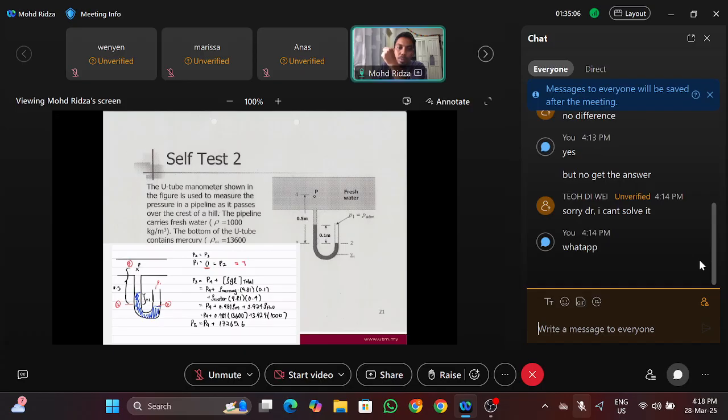rho. I think maybe you haven't applied it, because I think you assume 0. You have to use rho of water, because it's saying 10.3 meters of water. Rho g times 10.3, which will, I think, lead to 101,300 pascal, 101.3 kilopascal. Sorry. Okay, that's the first one. Instead of using zero gauge pressure, use absolute pressure.